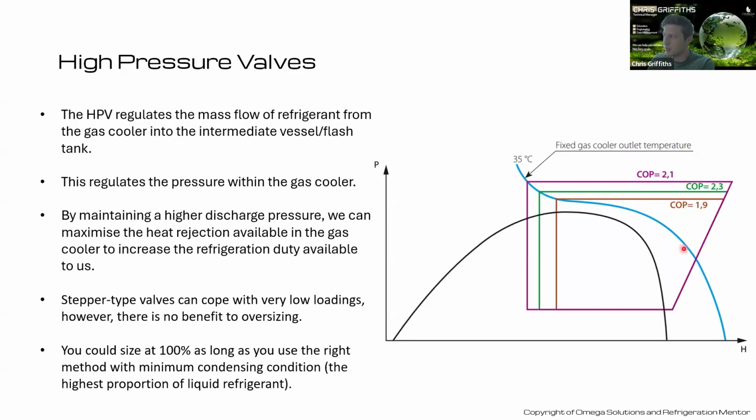we want to boost the pressure, we're going to use more electricity, we're going to put more power into our compressor input. But by sending it along, as we drop through that high pressure valve, dropping our pressure back down into our receiver and condensing our refrigerant back into a liquid, we now have a much higher quality liquid than we would have otherwise. Our fraction of liquid to our flash gas has reduced from maybe 60% flash gas there, 50 there, 45 there. So we're effectively getting, in proportion, possibly 30% more liquid than we were getting otherwise to go off to our evaporators and actually carry out our cooling that we need to do on site.